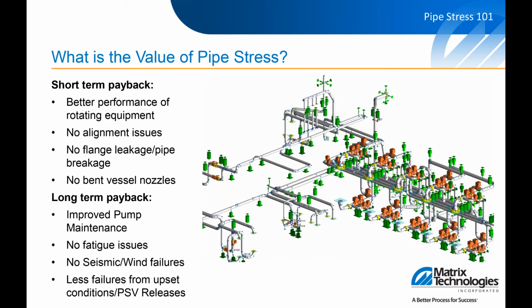You're not going to damage the casing, but what you're really concerned with on rotating equipment is those sub-thousandths of an inch clearances. So once you put that load on the casing and the pump casing distorts, then you start to see wear, you start to see rotating equipment maintenance damage. You'll see alignment issues as well.